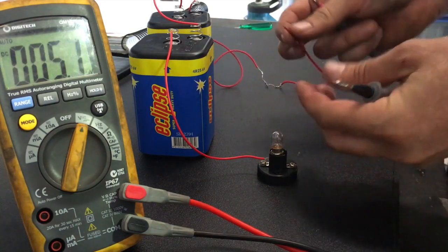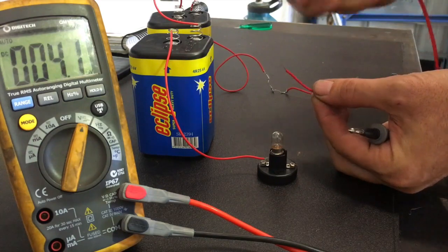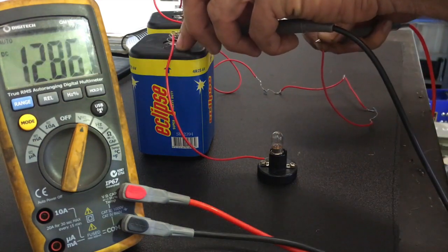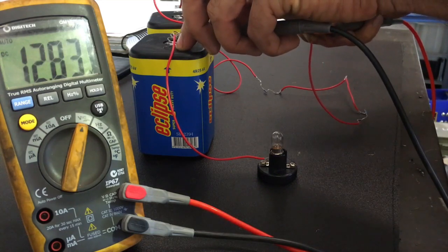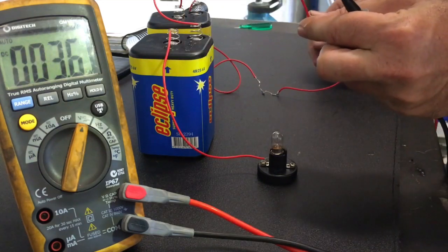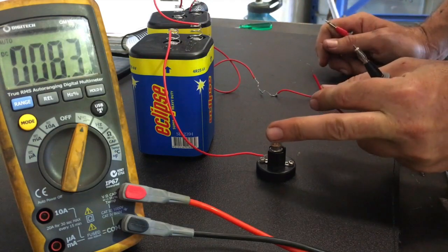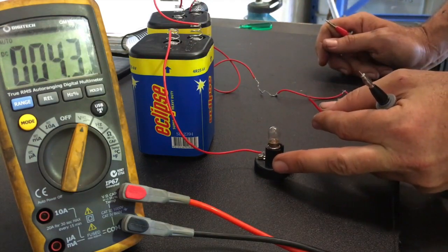So it's only, and the same thing goes if I had this wire coming to the front of the boat, I test this wire, I put the other one to my battery terminal, and I go, look, I'm getting 12.8 volts to here. I'm not. By the time it gets to this light, there's only 0.1 of a volt left to drop.